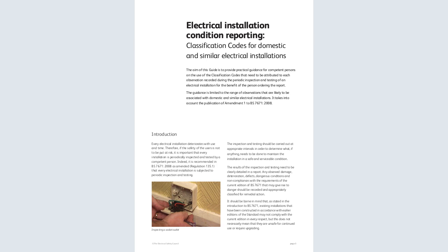And I remember telling you that when we are doing inspection and testing for these hazardous areas, the testing itself is always normally done like any other place. It is done like any other installation that we do. The inspection has a standard, and that is why last week we talked about the basic inspections that are normally done. We talked about the earth loop impedance test. We talked about the polarity test. We talked about the insulation test. And which is the last one that we talked about?